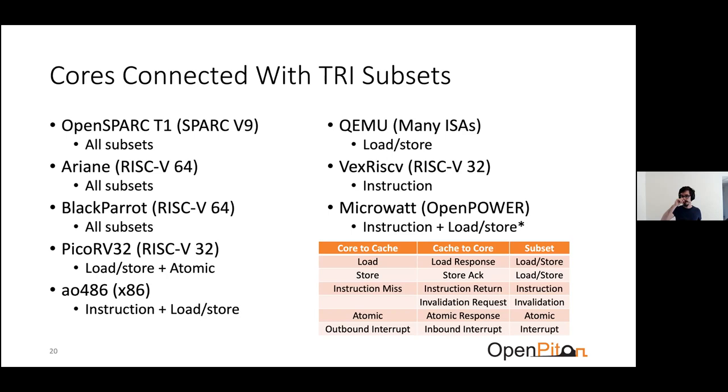And then the last one I'll note here is Manycore. So Manycore is an OpenPOWER CPU. And I spent a few days, I actually don't know VHDL, but I tried to pick it up for the purposes of connecting this core. And I was able to get to the point of implementing the instruction subset to a significant degree of completeness, and then some amount of the load store subset. So I could print like HE out of Hello World or something like that to you. But that's the amount of functionality that you could potentially get in a core that corresponded well with our design.